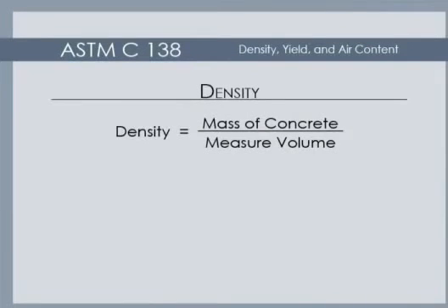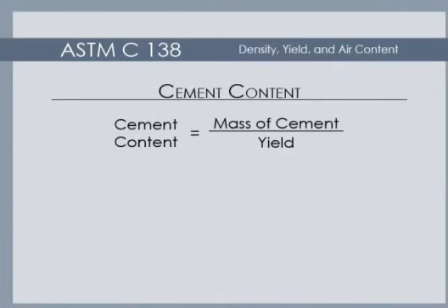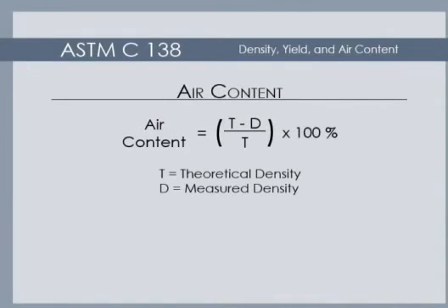Using the formulas found in the standard, compute the density, compute the yield, compute the cement content, and compute the gravimetric air content of the concrete.